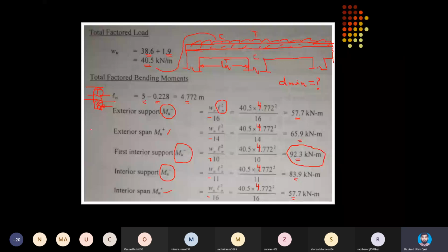However, in this option to fix the D minimum, if depth comes out to be more, because highest demand you are using to fix the D, and if architect is not allowing to go that much deep in cross section, then obviously there is no other choice except to go doubly reinforced in those portions where beam is behaving like a rectangular beam.